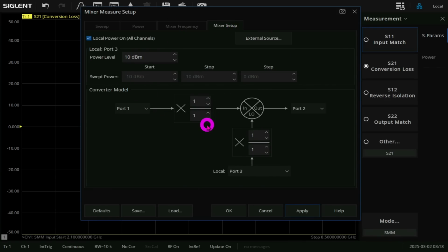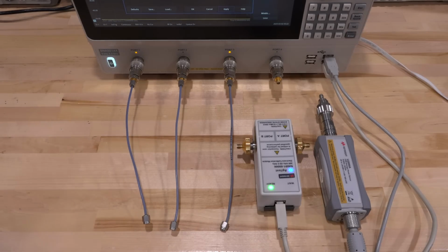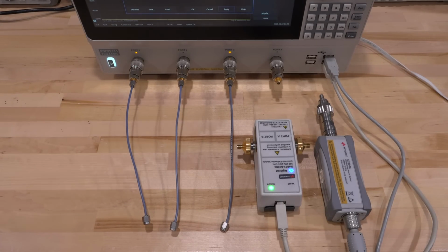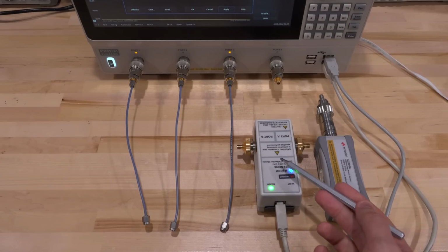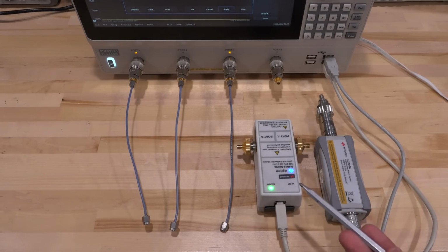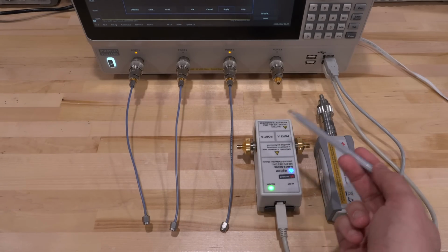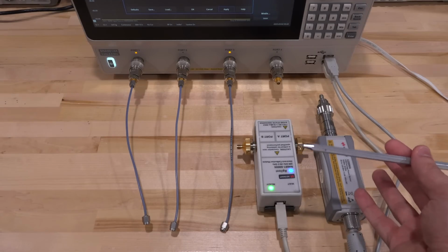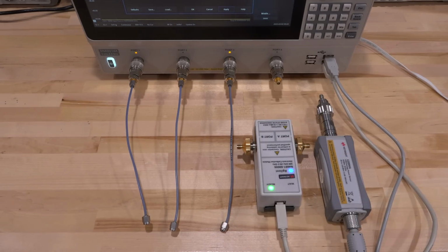We still need to calibrate the instrument. Now, unlike the calibration of a regular network analyzer, there are some additional things we need to worry about, which I will explain. The calibration using an ecal is pretty straightforward. We've done that many times before, and we will do this again in order to calibrate the ports so we can measure S parameters on top of making frequency conversion measurements.